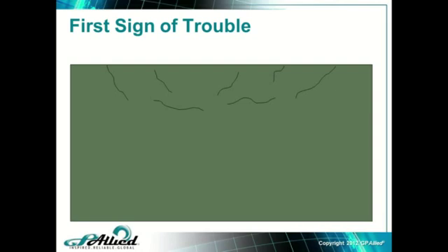I mean, that's just an unsafe practice because you don't know if that bearing's got a problem, and you could be about to lay your hand on something that's 300 degrees, which, you know, has been done. So for $69, you can get a spot radiometer at any hardware store, and you can measure the temperature of something for next to nothing. That's the way it should be done.